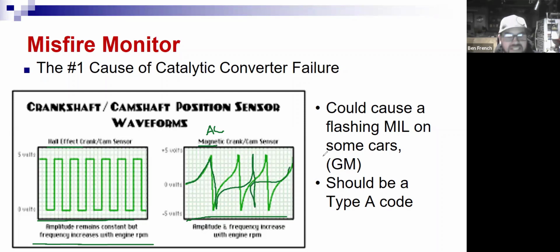And the computer can then see that and go, oh, the crankshaft is slowing down right after cylinder 7 in the firing order, because the firing order is programmed into the computer. So it looks for that gap of where all of a sudden it slowed down, and then it looks at the firing order. It's not just what the crankshaft position sensor is saying, but what's the camshaft position sensor saying? So it looks at crank versus cam versus what's going on with the frequency. And from there, it can figure out where there's a misfire happening. That's how most all misfire monitors work.